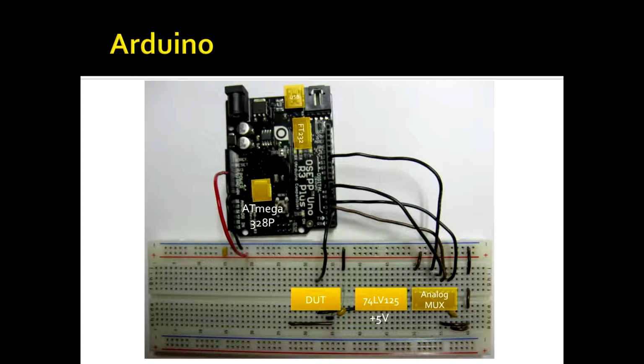It automatically goes through a divide by 2 as soon as you turn any of those timers or compare features on. So before I even started, all I could do was 8 megahertz signals out of this thing. If your device is running at 2 or 4 megahertz, that might be enough, but if your device is running at 32 megahertz, then obviously this isn't even going to help you. So it just wasn't flexible enough.